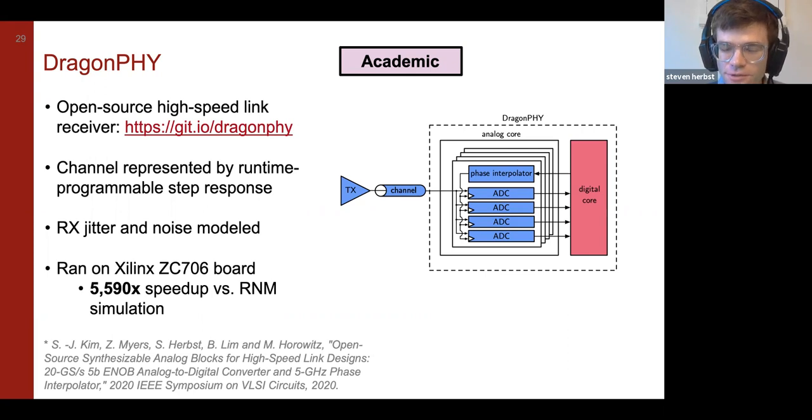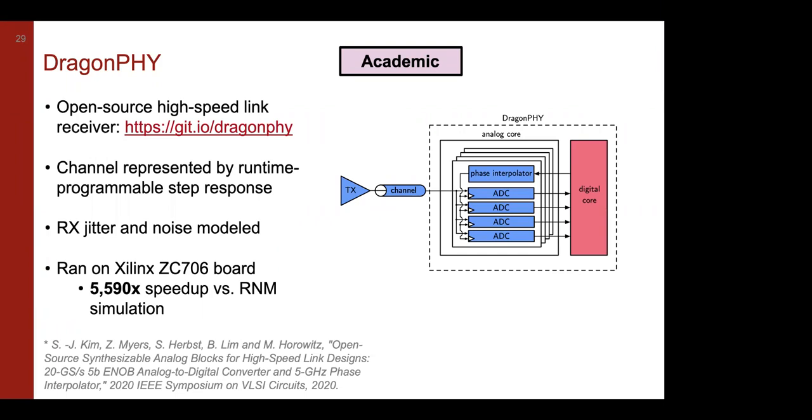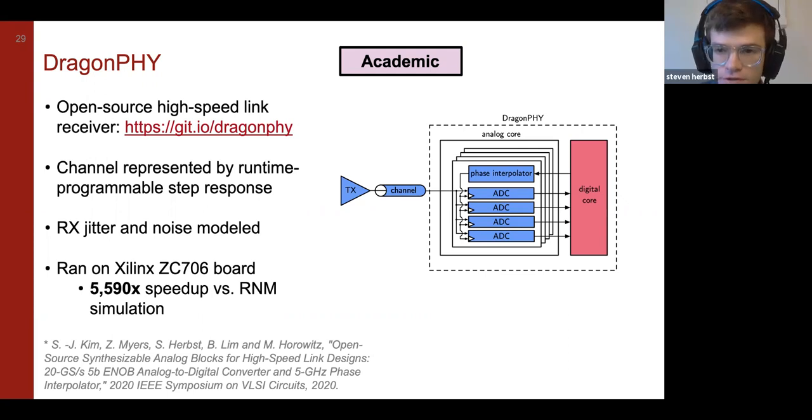And then in addition to that, we should have tools that can generate synthesizable analog models so that they can feed in upstream of that digital emulation process. So yeah, I think that definitely seems to be an area where there's still a lot of work that could be done on the tooling side to just make it easier to handle multiple clocks in a design without having to really go in depth and learn the clock tree as an outside user. And there's also a lot of just syntax discrepancies between FPGA synthesis tools and ASIC synthesis tools that take a long time to smooth out.